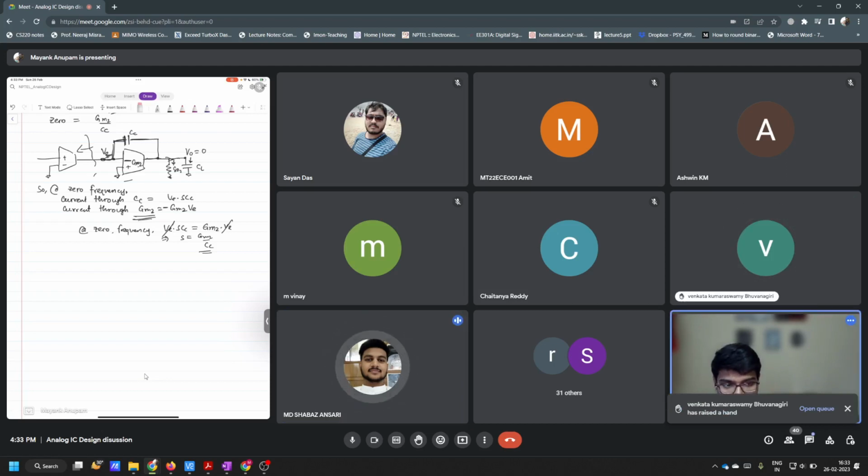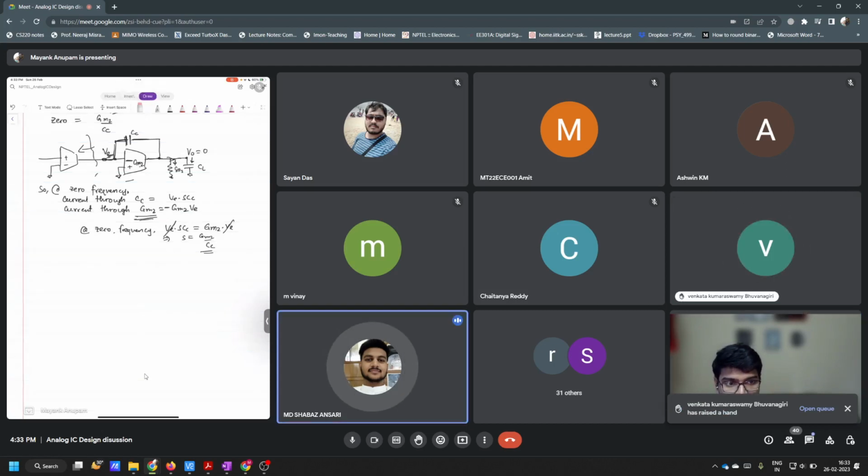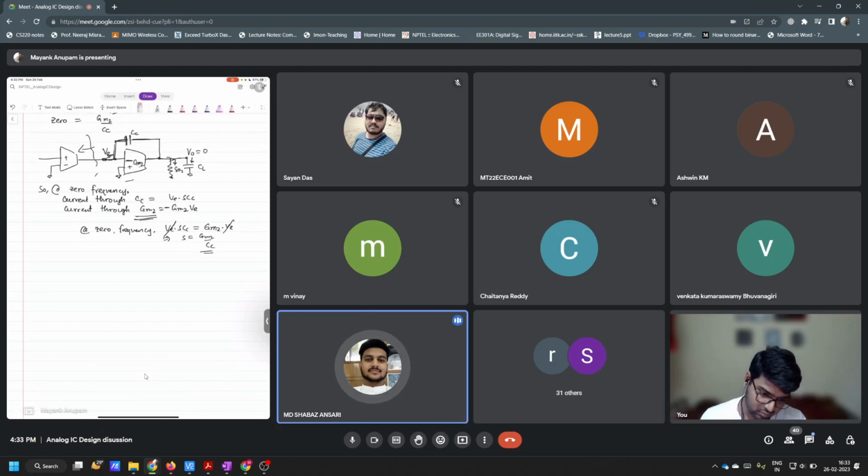Sir, I have a question related to week 5. Yeah, go on. Sir, in the last lecture you told that if you add a resistor divider for the k gain, then the position of poles and zeros is not changed, but the omega u loop is changed. Yes, correct. And the phase plot is also not changed.